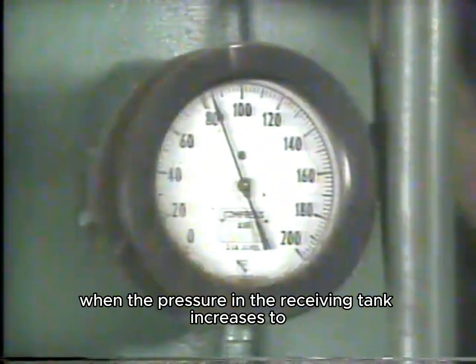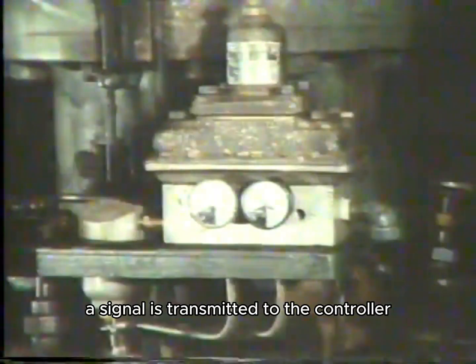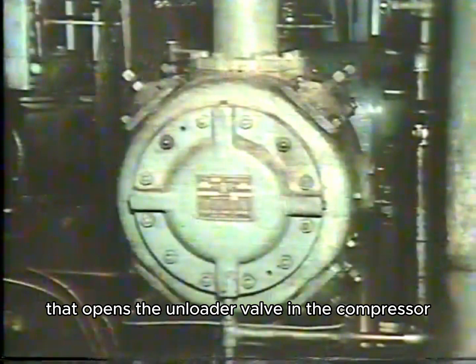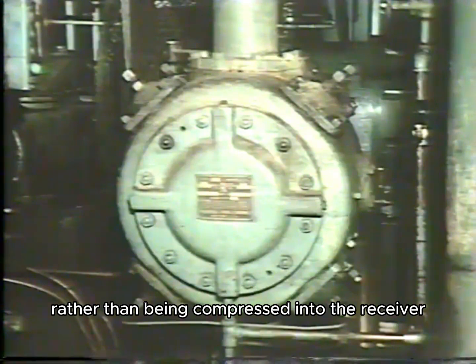When the pressure in the receiving tank increases to the upper range of 100 psi, a signal is transmitted to the controller producing an output signal. That opens the unloader valve in the compressor, allowing air to escape rather than being compressed into the receiver.